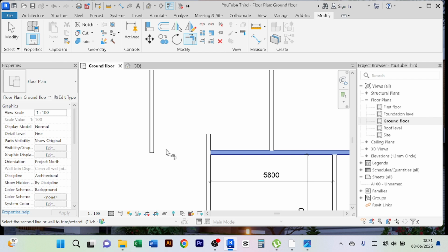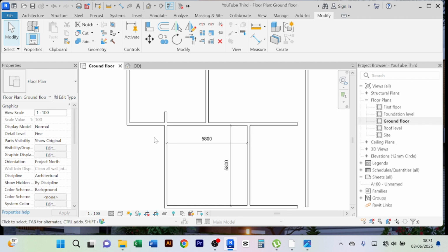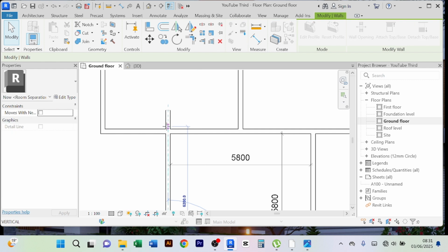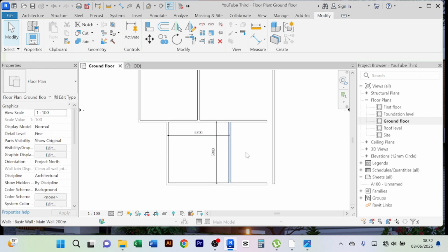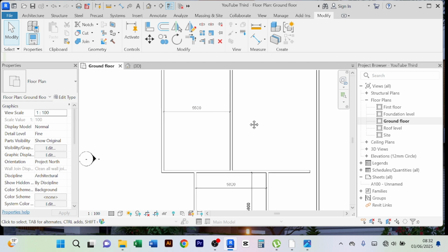This line will tell you that this wall is going to connect with this one. You connect. So there they have connected. This one, the excess part, I can just drag and bring it here. When you see these lines, this center line is drawn, you can leave it there. So this is the file we have drawn our house.